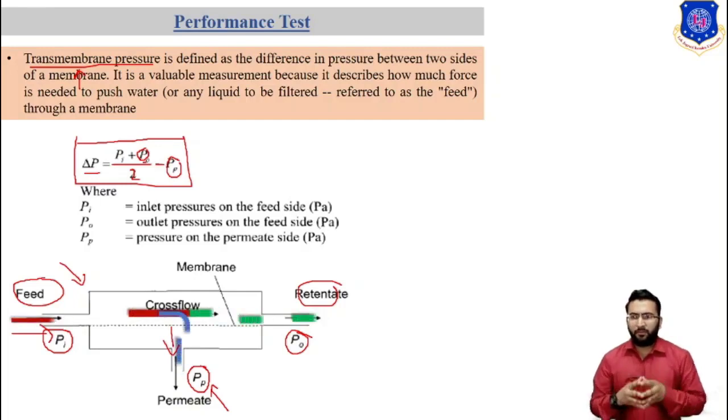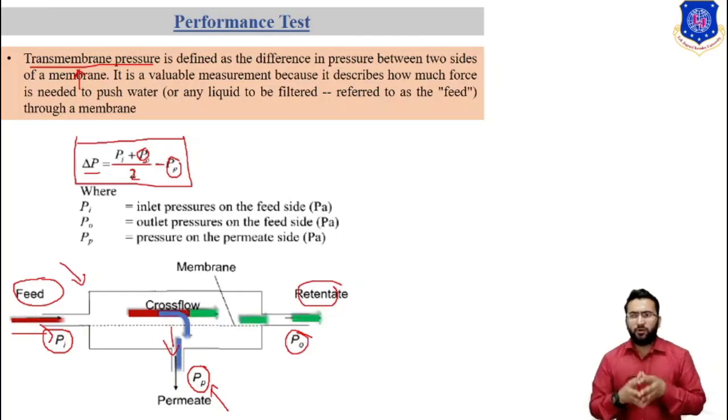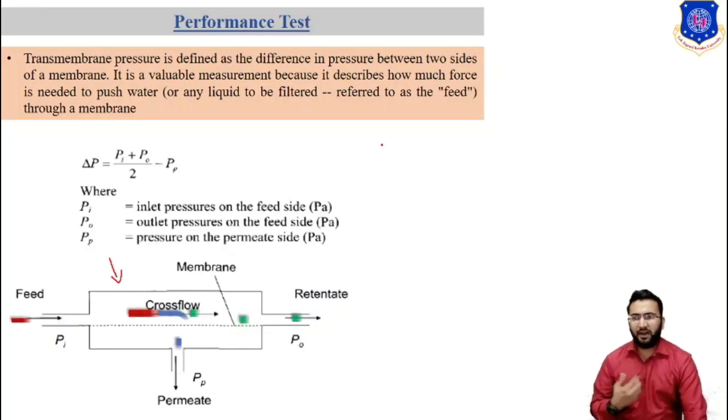The flow rate through the membrane or filter is measured at a single transmembrane pressure, and the pore length and overall membrane porosity must be assumed or measured by some other means. All the flow is assumed to go through a single size pore. Using this membrane filtration setup, we can find the permeability, flow rate and various resistances during the membrane separation process. So using this setup, we can find various performance test parameters such as permeability, retentate and various resistances during the membrane separation process.